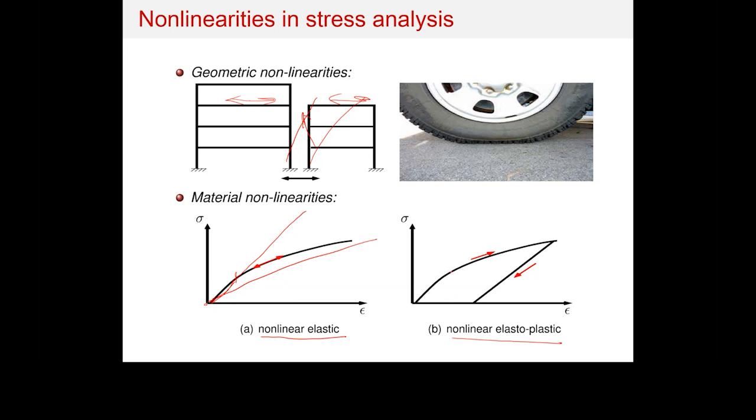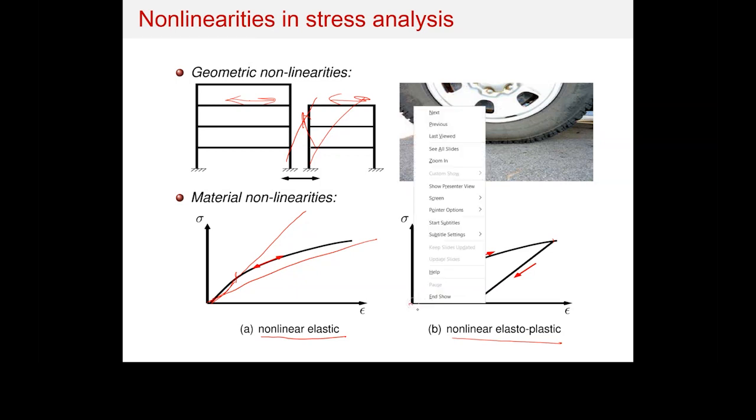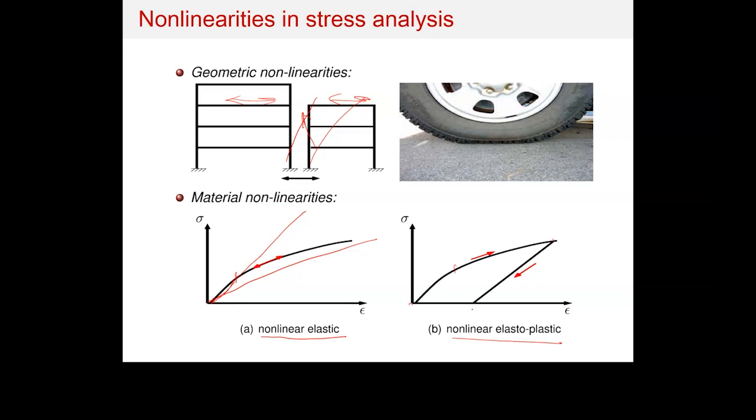Because in the nonlinear elastoplastic, once you exceed the yield point, and you get to this point, for example, and you relieve the stresses, this is not going to come back to zero residual strains. It's going to fall back, but there'll be some strains remaining inside your material, and this is going to be a significant amount of strain.